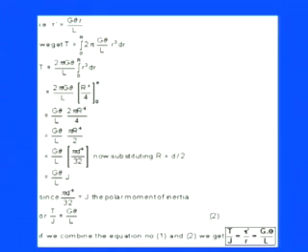So now we have the torque equal to G theta by L into J, or we can also write T by J, the applied torque divided by the polar moment of inertia, is equal to G theta by L.